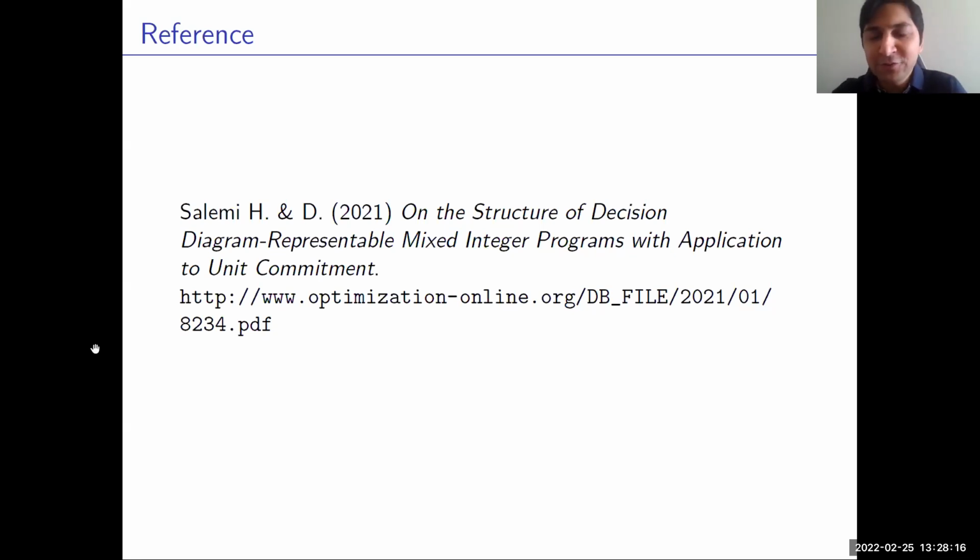Yeah, thank you. That's a great question and a very interesting point. That's right. Decision diagrams by nature, when we build them, use dynamic programming kind of approaches, right? There are stages and state values. In fact, how we build this unit commitment problem, for instance, definitely uses the concept of state values and so on. The main difference between decision diagrams and dynamic programming is the so-called curse of dimensionality. For dynamic programming, the concept of relaxation and restrictions, as we have in decision diagrams, was not really considered in the past. And that is really what gives an edge to the decision diagram, not just for this problem, but for many other problems that we see right now.